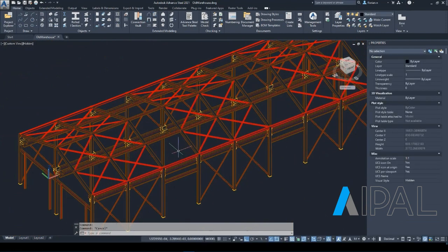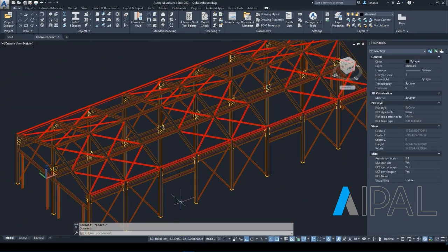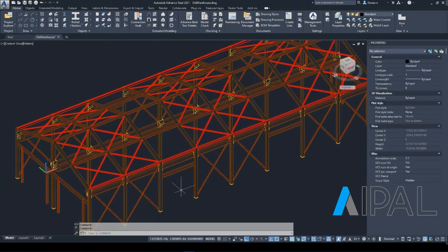The sketch method is a bit more conceptual. It has just about maybe 1/10 of the amount of code, and doesn't ask so many questions. So let's try maybe this one here. What we have here is Solid2Object, and let's use the sketch method. Maybe we also have a couple of rounding issues, or the sections are not quite perfect coming from this old CAD file. Let's say we work with a tolerance of 3%, maybe plus minus, which is literally nothing at this point either. Let's ignore any questions about the flats, because we're just dealing with the bracing here.